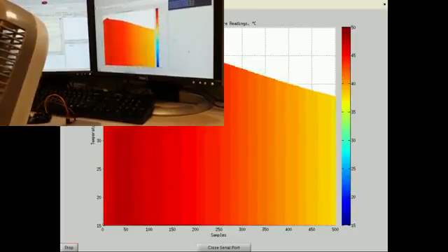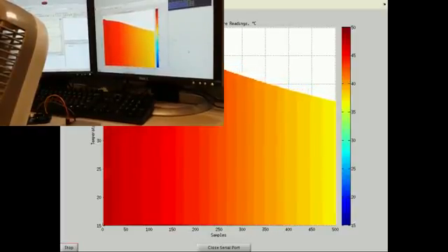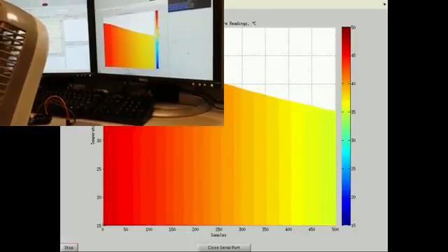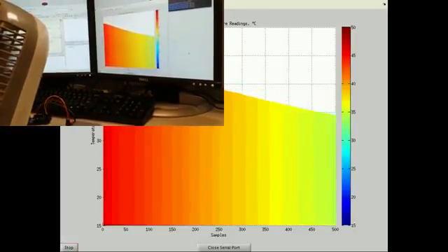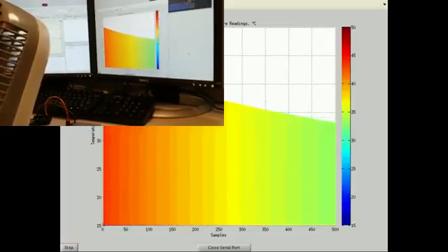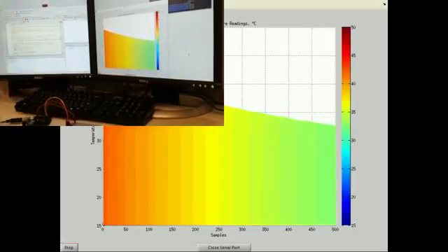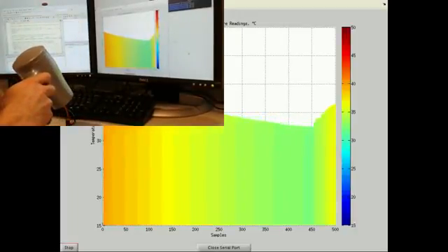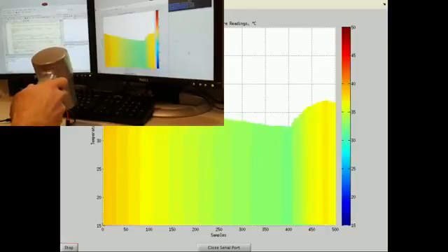Thermal paths run through package leads and the plastic case of the TMP102. Due to the lower thermal resistance of metal, the primary path is the leads of the IC, which are affected by the ambient air temperature. As this temperature is varied, Newton's law of cooling is illustrated.